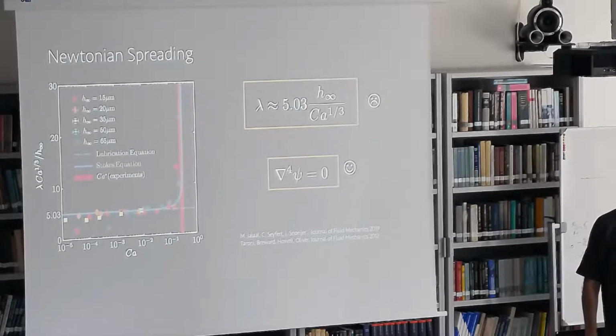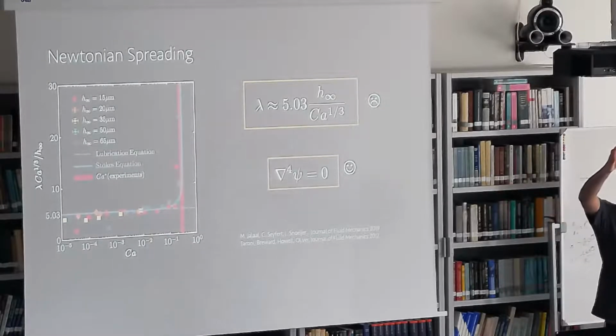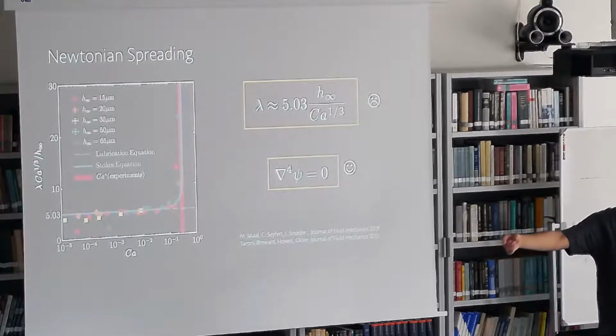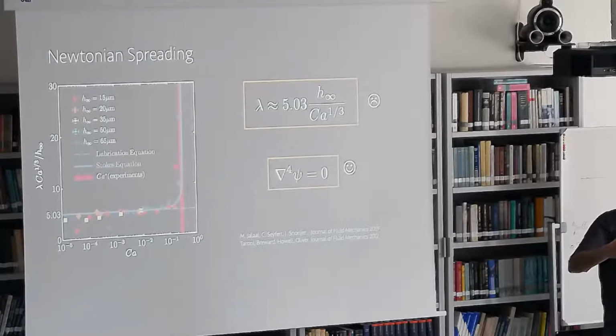It's a combined thing. There are two questions. The curve that, for instance, I showed you, where the final radius goes down at the moment of arrest, I only showed as a function of temperature gradient or heating rate, but you can plot it in a three-dimensional curve, including humidity, for instance. So you can change the thermodynamics of the system and the final radius changes, because evaporation has become important, in fact.